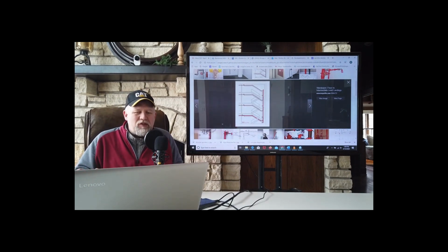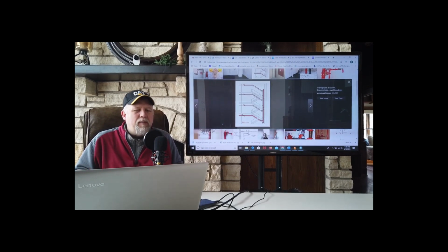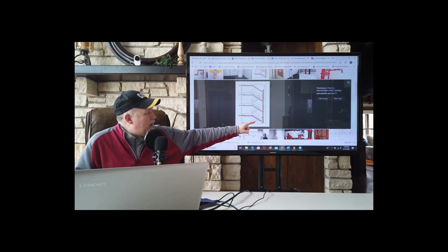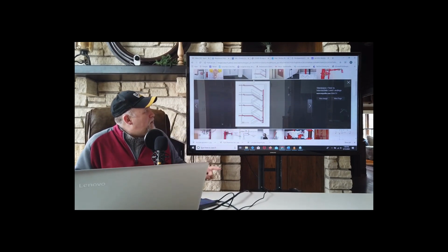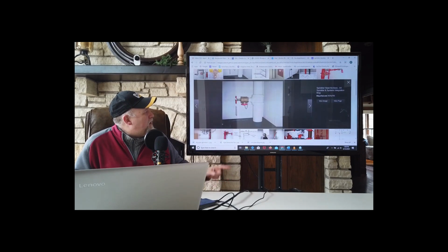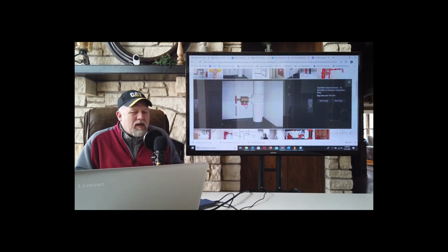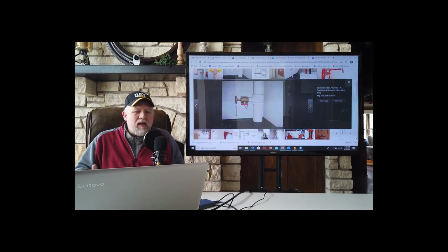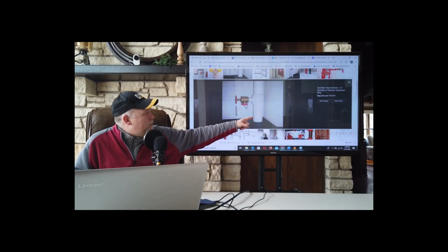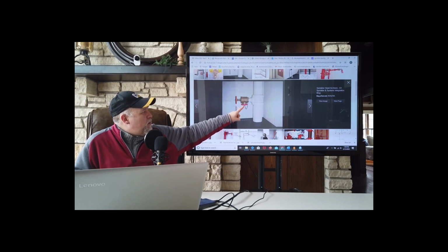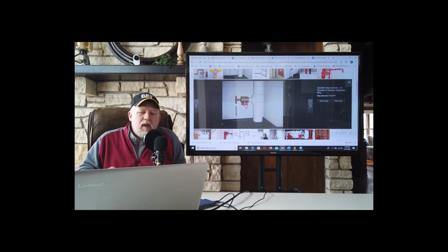All it's doing is just a vertical riser of pipe in the building that the fire department is going to connect to, and it goes to hose connections in the stairwell like this one. In Town Engineering, if you go to the south stairwell, you'll notice this big pipe in the corner, and then occasionally there are these brass valves with thread protectors on them.